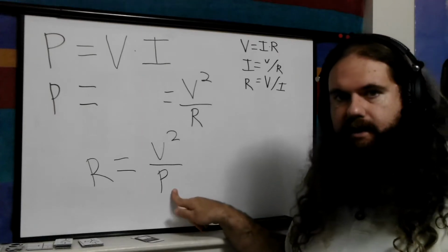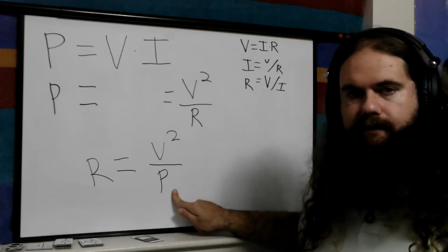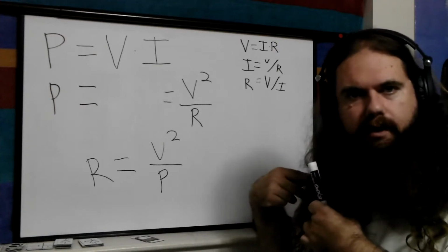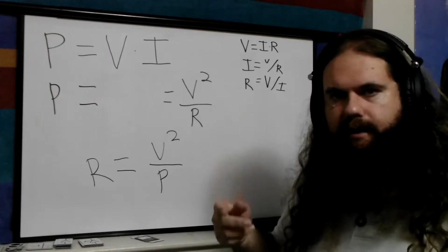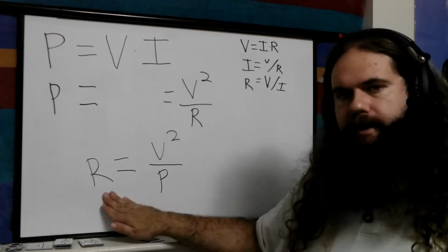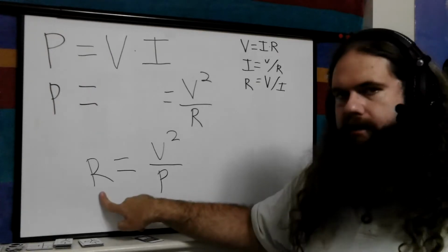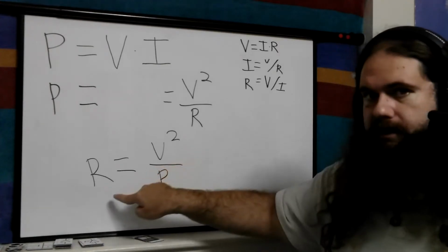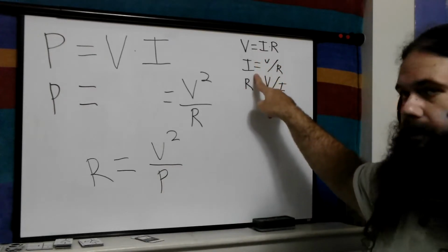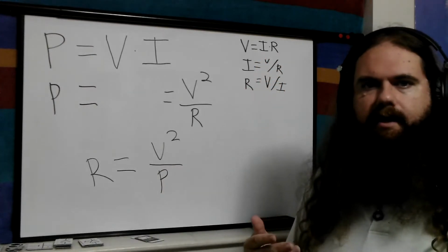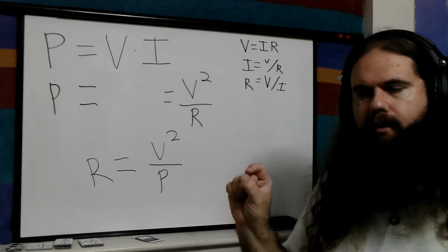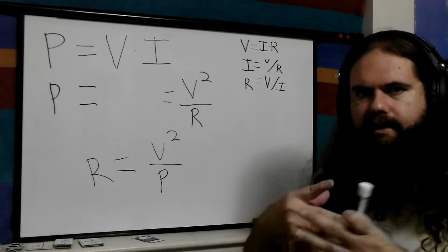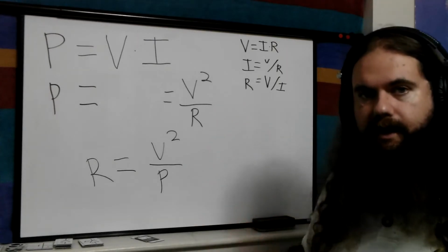So if you need a certain minimum current, then you can just use the full power resistor. Or if you want to deliberately limit the total power usage of your circuit, for example, you're making a low power device such as something to be worn on the body, like a little blinking light setup that's sewn into your clothes, then you can try and minimize the power and get the resistor value and then see what current you get, because then you have the voltage and resistance. You can calculate the current to make sure, let's say, whatever device is plugged in after requires a certain minimum current. So you could then use this equation. You just take these equations and go back and forth until you get the thing you want.